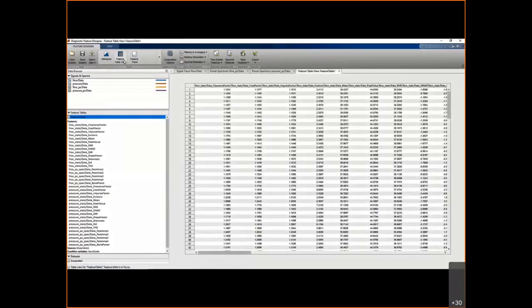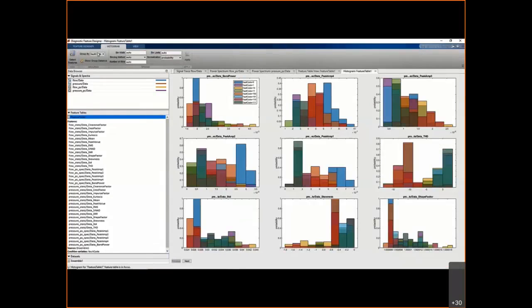Now the question is which one is more sensitive for your machine learning model. Because there are more than 20 features, even though it depends on your signal, in this case it is more than 20. So how do you rank them? This is just a visualization, a histogram-based graph. We want to know which signal is more relevant or more sensitive to your data. You can go to the Rank Features button here, where we rank the features that you can use to train your model after this.